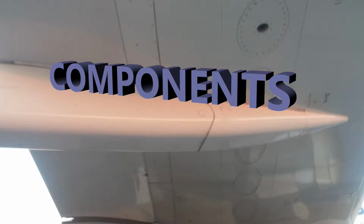There are 2 full level sensors, and then there are 3 sensors for if it's under full level. There are also your overflow sensors, located 1 in each wing surge tank. And then of course you have the IDG, the integrated drive generators. I didn't mention that earlier, well, I have. You've got shutoff sensors that are located 1 in each wing tank.